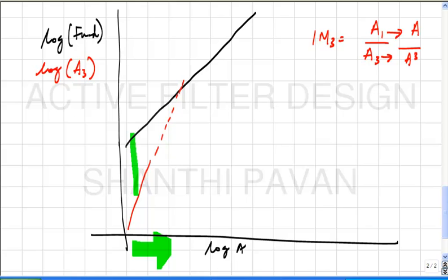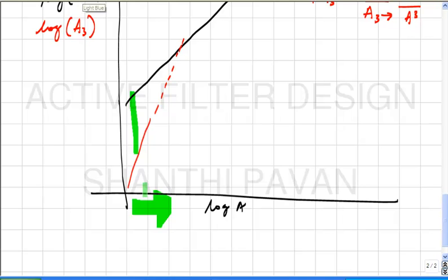No. Please note that here the distortion components and the input components are so close that they will pass through the same transfer function regardless of what you do to it. So the output, from the output of the chip to the measurement equipment, could be 2 kilometers long, but since the distortion components and the input tones are very close in frequency, whatever was the ratio of the distortion to the fundamental here will be the same at the output also. So an intermodulation distortion measurement is a lot less prone to error because you don't need to worry about the frequency response of the test setup. You understand?